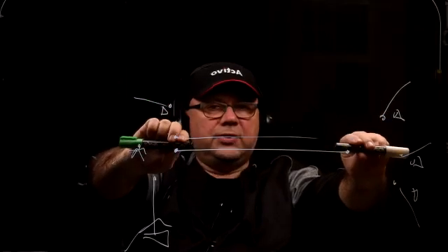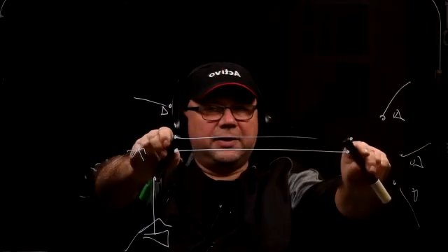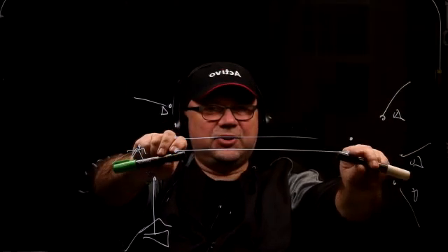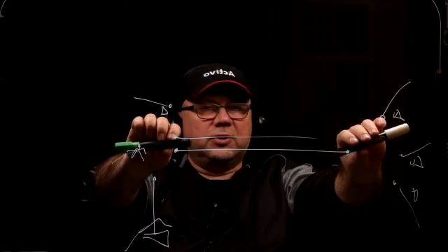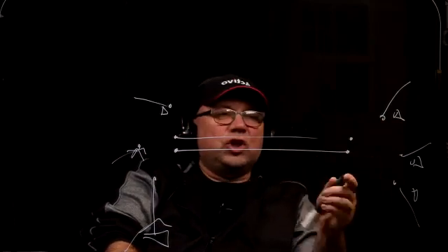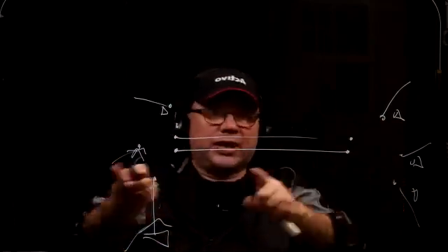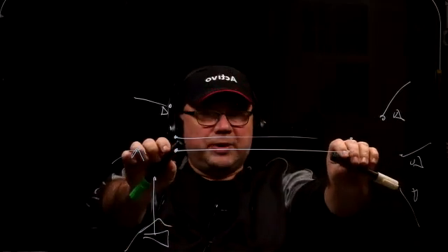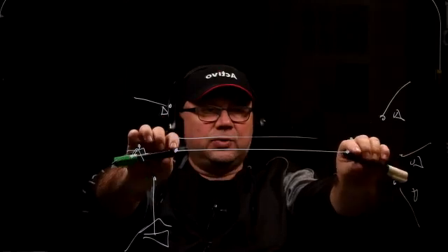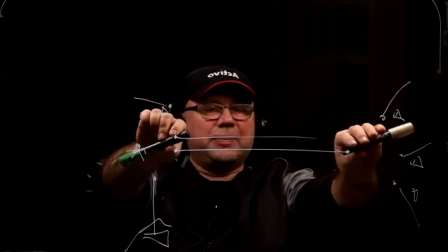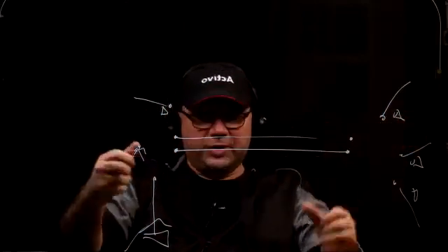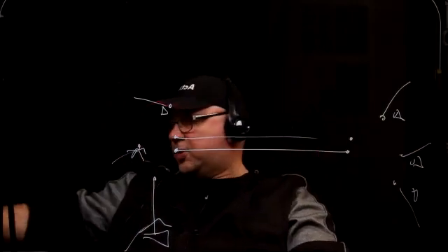Now, if you make this thing switch at a very fast speed, and if they're synchronized, all those breaks and all the switching are not going to be noticed because the switching is happening very fast. Those people are just going to think that they have a continuous connection. So that's time division multiplexing. Each one is connected to the other one link at a time, but the switching is happening very fast, so they hear as if they're having separate connections. But those things have to be synchronized. That's called time division multiplexing.